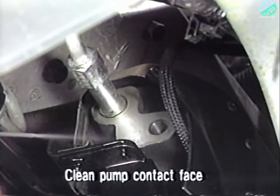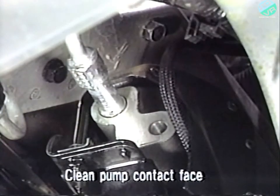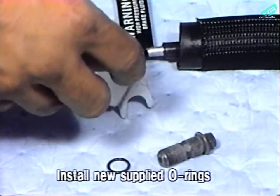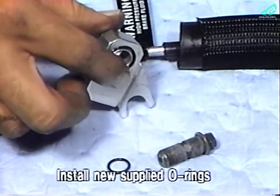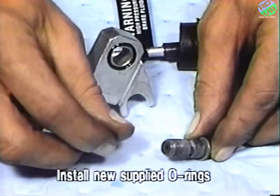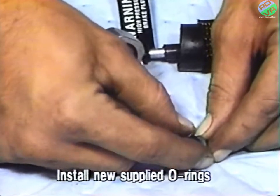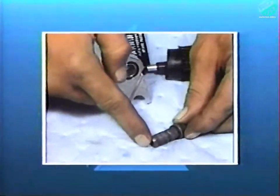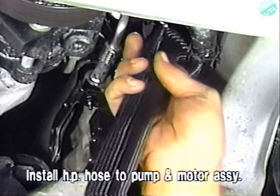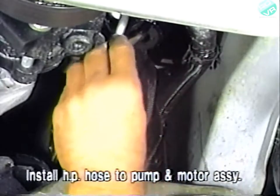Clean the pump contact face for the high-pressure hose with Mopar brake parts cleaner or an equivalent. Next, lubricate the supplied O-rings with brake fluid and install the large O-ring on the connector block face and the small O-ring on the cleaned banjo bolt. Now, route the high-pressure hose along the low-pressure hose up into the engine compartment, being careful not to twist the hose.